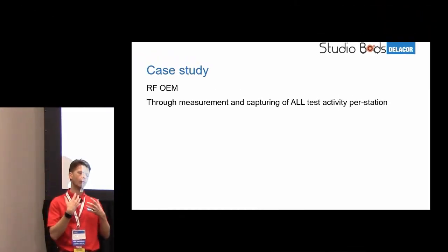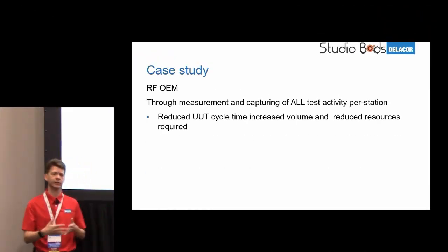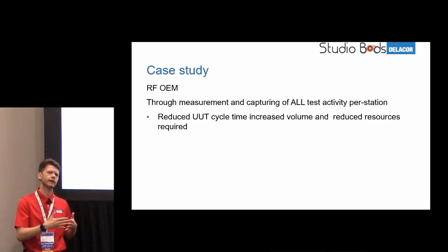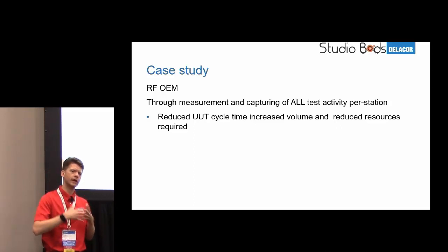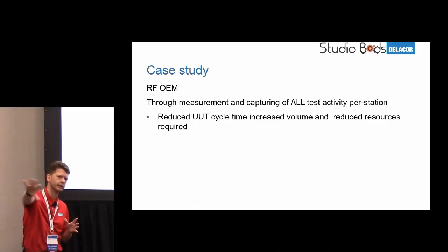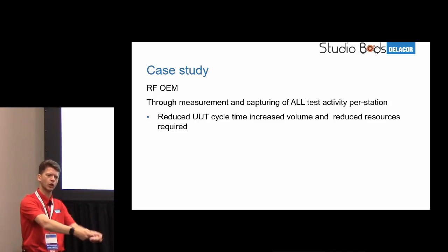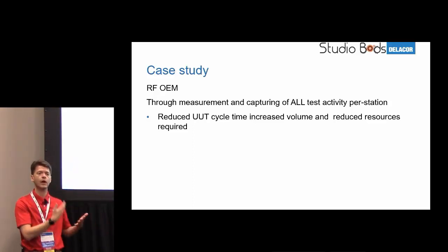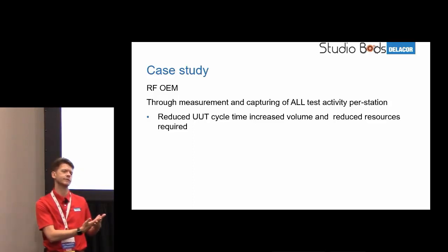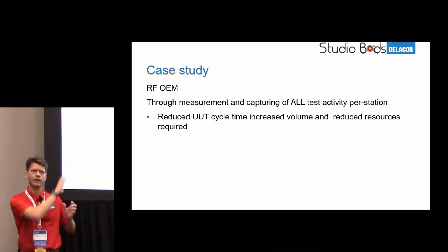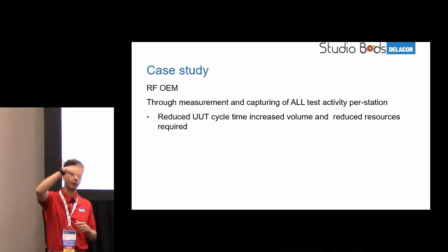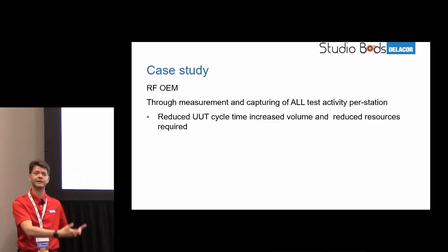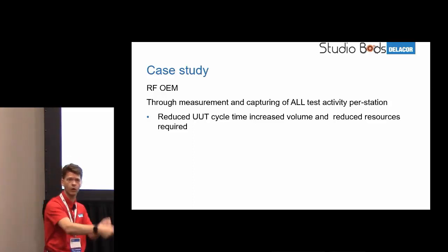What came out of OEE was that, in between performing tests, the test station was actually sat idle for several minutes because the test site operator was performing some other operation. He was loading a unit onto the next test fixture. So it was sat idle for several minutes, not performing value-added activity. The first thing they did was put alarms, very rudimentary, but alarms and sirens on top of the test station to draw attention to the fact that it needed servicing. It needed somebody to come and load another unit on there.